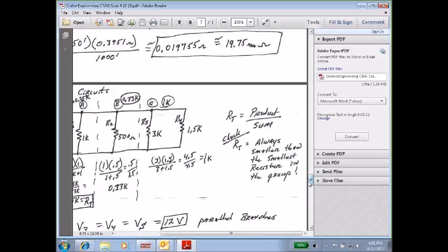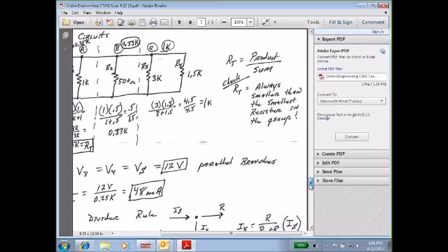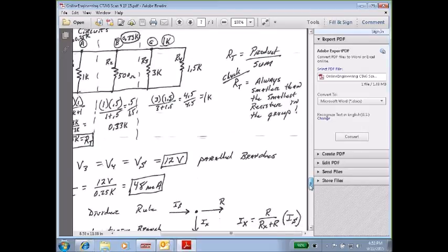I use this method because, as far as meters and so forth, we're actually measuring resistance, and we can just use the numbers that we measure directly. But the reciprocals will give you the same thing. But I always teach it as total resistance is product over sum. Just using resistance, then I don't have to reciprocate everything. But I think that's basically a matter of preference. That's the way that I learned it years ago.